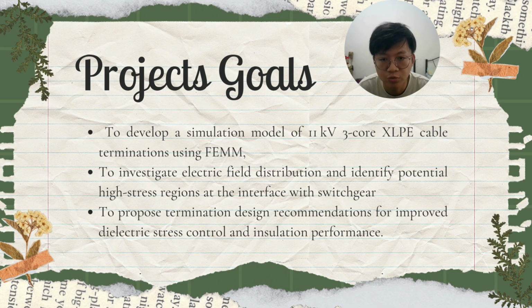Therefore, for our project goals, we would like to develop a simulation model of 11 kilovolt 3-core XLPE cable termination using FEMM, and to investigate the electric field distribution and identify potential high-stress regions at the interface with switchgear. Lastly, we propose termination design recommendations for improved dielectric stress control and insulation performance.